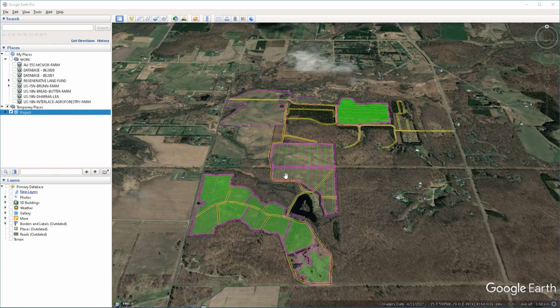You would first have to reduce them to basic objects such as polylines by, for example, exploding them using the explode command. Now we can take a look at the different plugins that are available for the different versions of AutoCAD. So whether you're using the standard AutoCAD, AutoCAD Map 3D, or Civil 3D, you can still use those plugins to speed up your workflow.